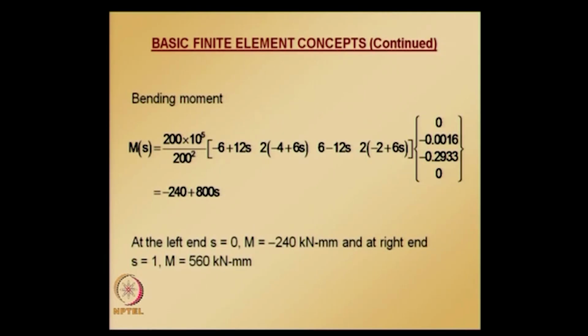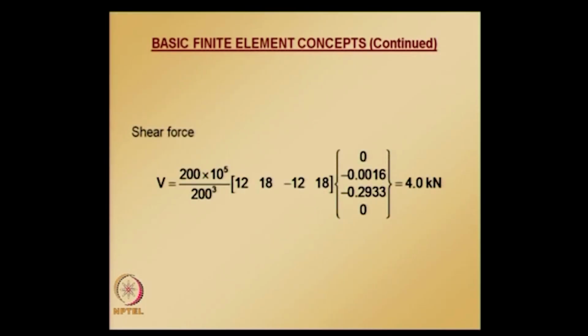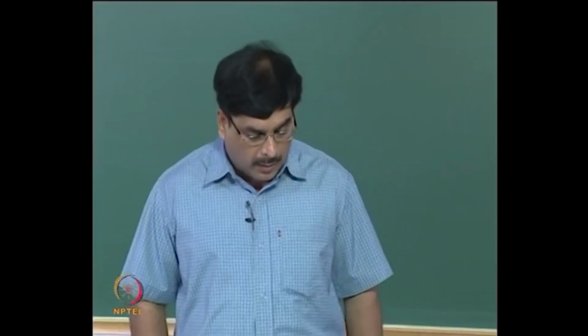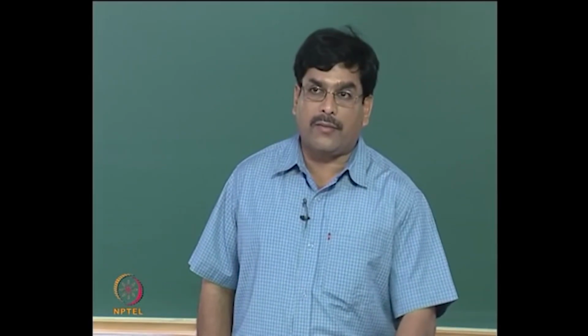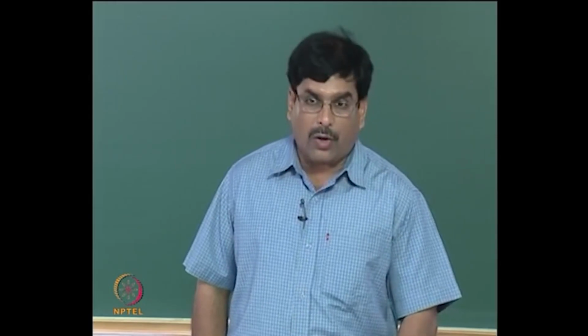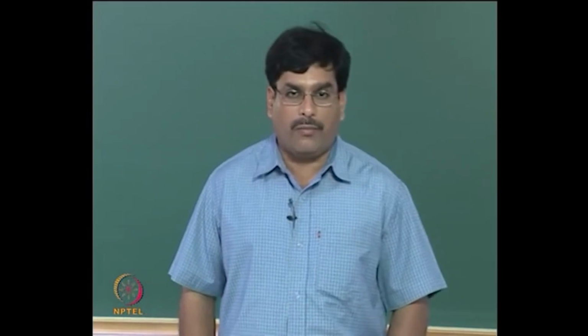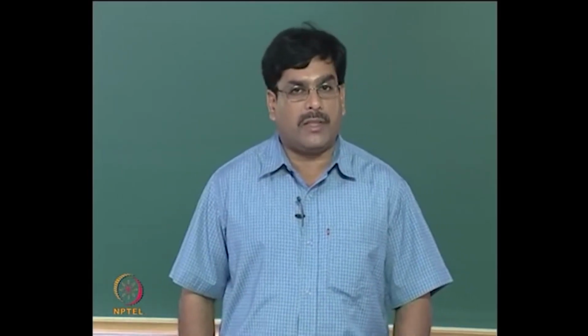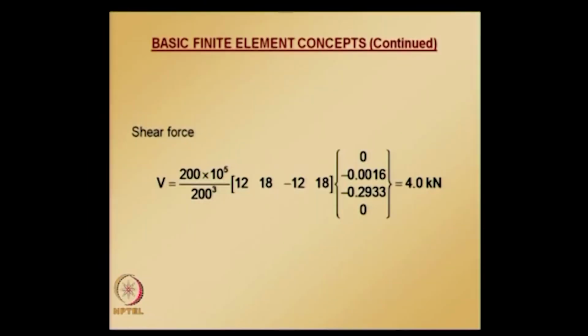And now shear force is again constant over the entire length of element 2. Please note that whatever shear and bending moment we calculated are all internal shear and internal moment values. So whenever we draw this or put it in the form of a plot, we need to follow the sign conventions corresponding to the internal moment and internal shear that we already started out with.